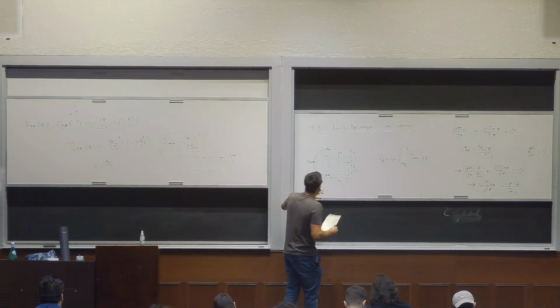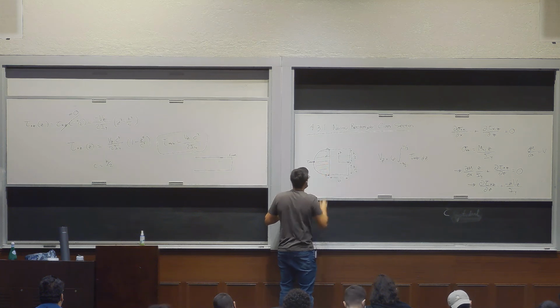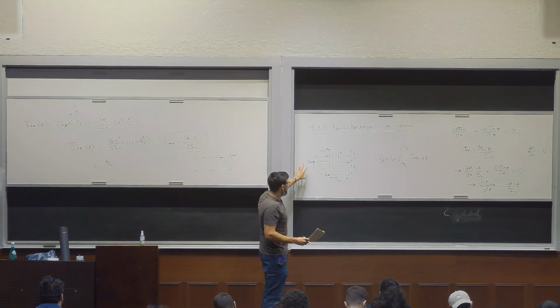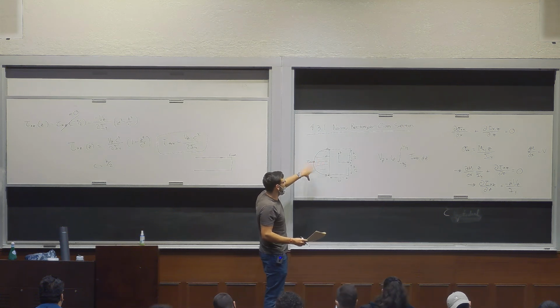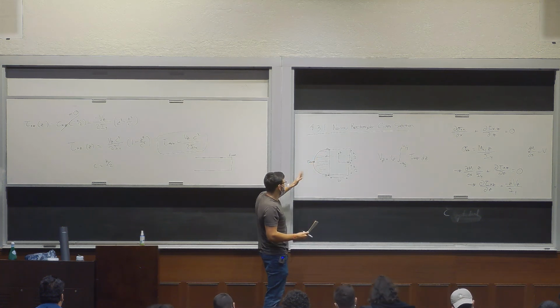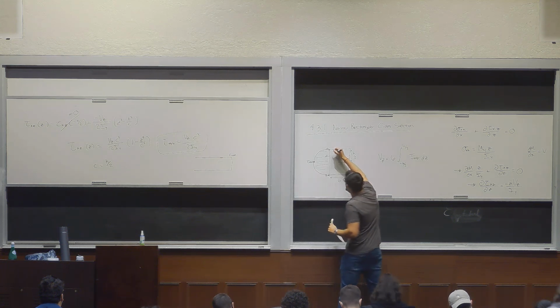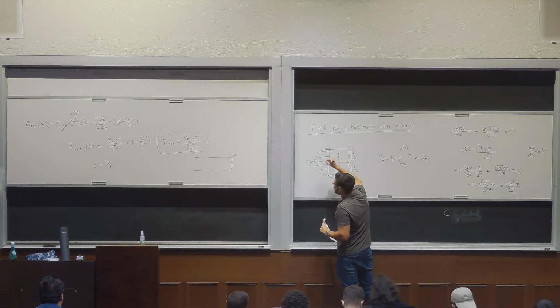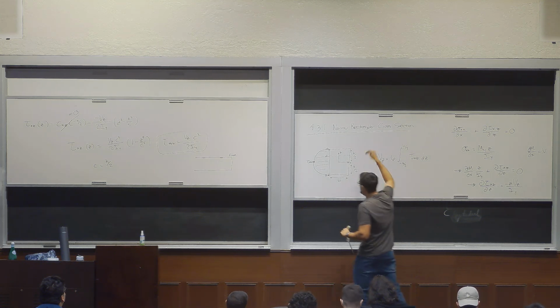A lot of times people get confused with these diagrams, where I draw the magnitude of the shear stress kind of to the side. This is not telling you anything about the direction it's occurring in, just the magnitude. If I drew it as a line, it would still say what the magnitude is. The actual distribution, if we draw it as arrows, in this problem, I don't know the direction of Vz, but let's assume it's pointing down.